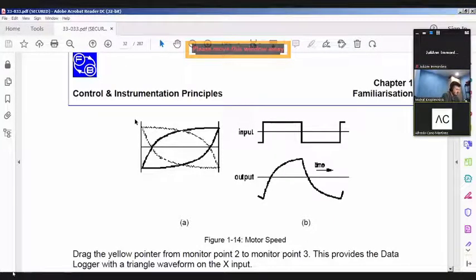You want to keep it at a fixed speed, right? So in this case, the integral would come more into play. Now, for example, in an elevator, you don't want these fast transitions where you have a lot of overshoot. You want to slow it down, and for that you use KD, derivative or velocity feedback, right? Depending on the system that you are trying to apply this feedback on, you may decide to emphasize one action more than the other. You cannot just simply max them both out and expect the response to be the best possible.